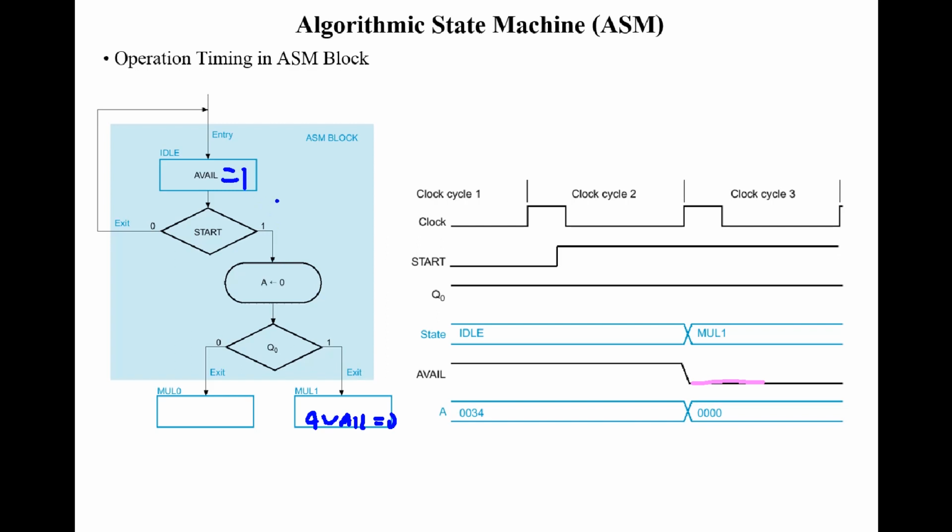In practice, many systems have many outputs, so it's not convenient to write down every output as 0 or 1. So often we write only the active outputs in the state box. If an output is not in the state box, that means that output is not active.